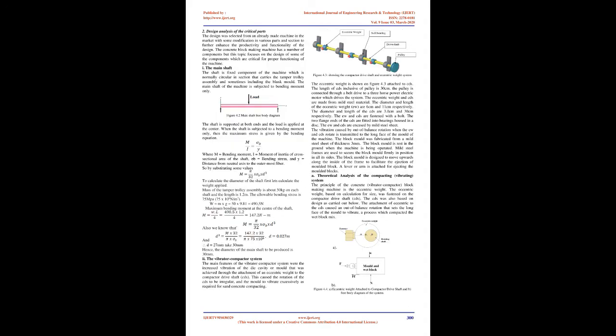It reduces time and energy consumption, because it is almost the same time and energy which is used for producing 1 or 2 blocks at a time to produce 4 or 5 blocks. Amount of damaged blocks is minimized due to the avoidance of pallets and improvement of the sliding mechanisms. The overall size of the machine is minimized by removing unnecessary parts of the existing medium machine like supporter of the tamper, length of the frame, size of hopper and size of tamper trolley guide shaft for easy usage.